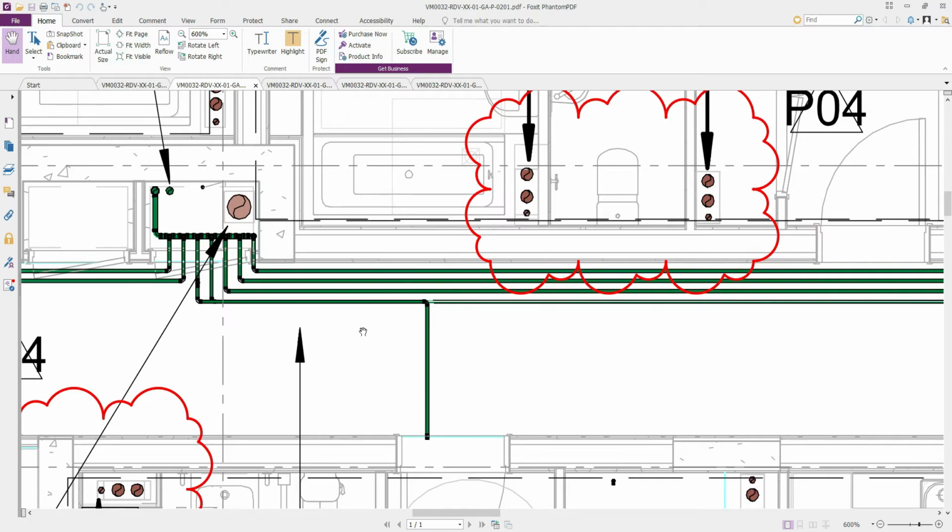Again, it depends on the project, as some pipes may require certain fixings, such as LTHW may need expansion anchors, and you may need to keep 75 mm. It depends on the anchor's size, etc. But for the sake of this video, I'm gonna keep it simple.